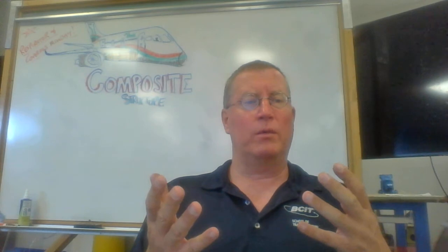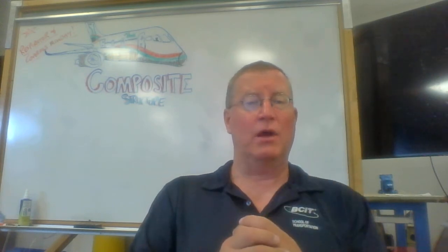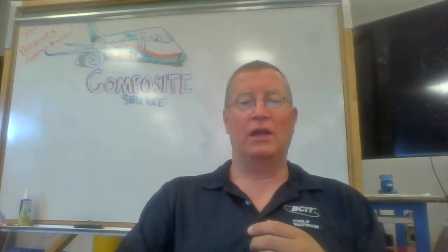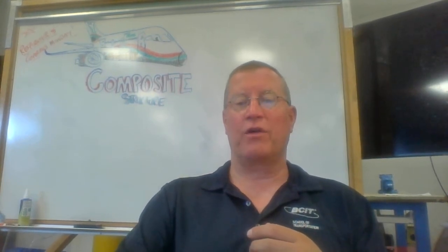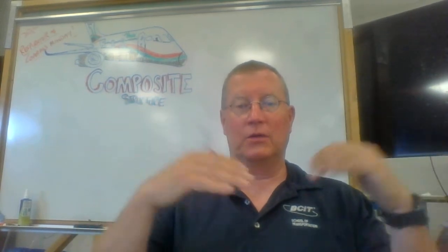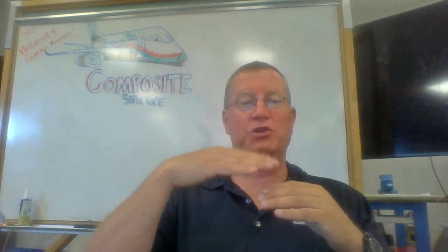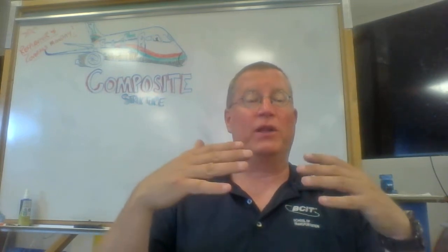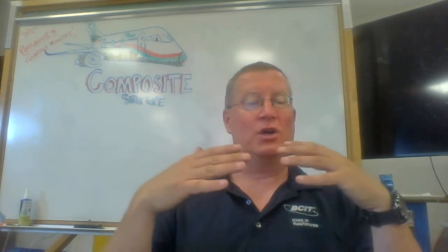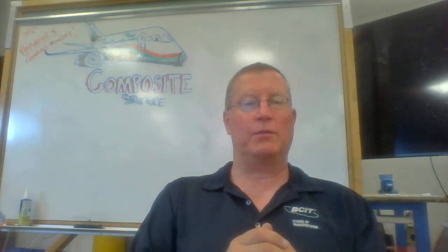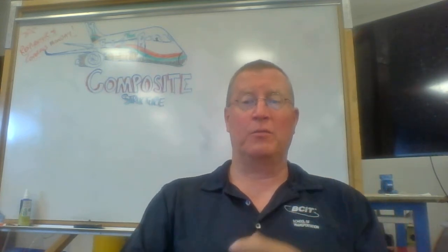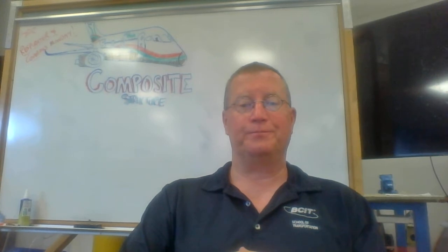If it's a non-loaded component, we don't necessarily have to worry so much about bringing back strength. And so we would move to something like a scarf repair, where it's literally take the material out down to the delaminated layers, and then we're just putting patches in as fillers. It's more an edge-to-edge contact, which doesn't give us the same degree of strength, right? But still may be strong enough for what we need to do.